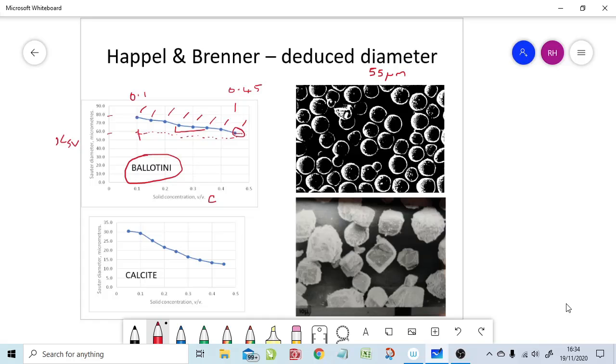Well, the good news is, if we were to use this value in our design, it's actually going to give us an overestimate of the required area for the design. So there's no disadvantage by using a low value of particle size in the equation, whereas arguably a higher value of particle size might be more relevant if we're operating under just a restricted range of concentrations.